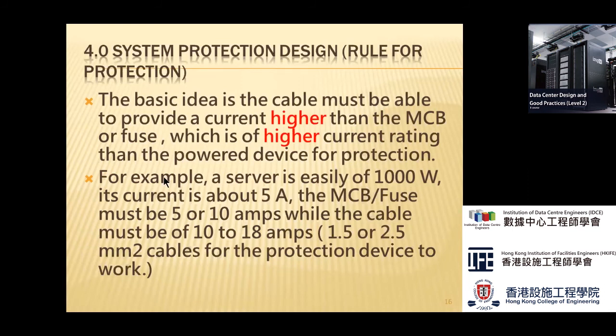However, if you want, you can use the highest size of the cable, right? To protect the protection device if you want it. But I think here in this case, if you only need about 5 amps, your 1.5 mm square cable should be sufficient, because a 1.5 mm square cable can provide something like 17 amp maximum.